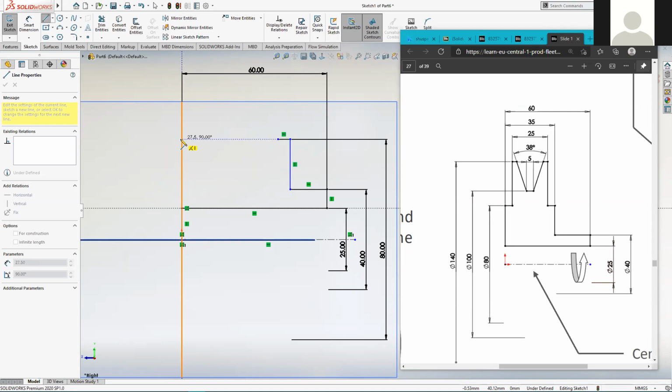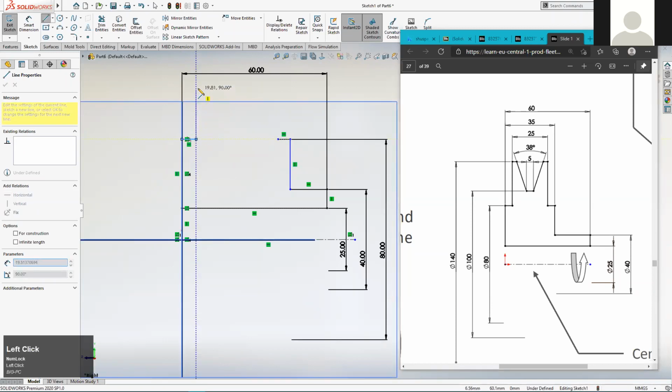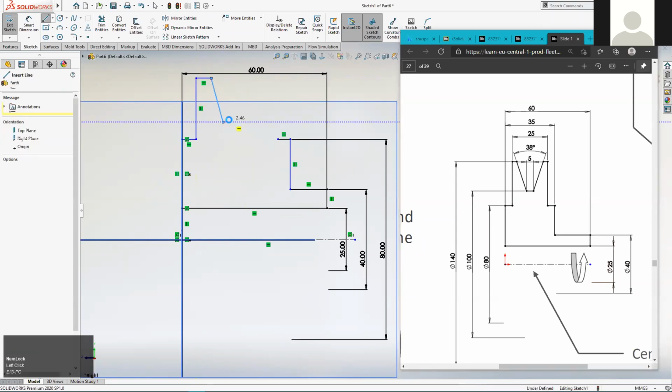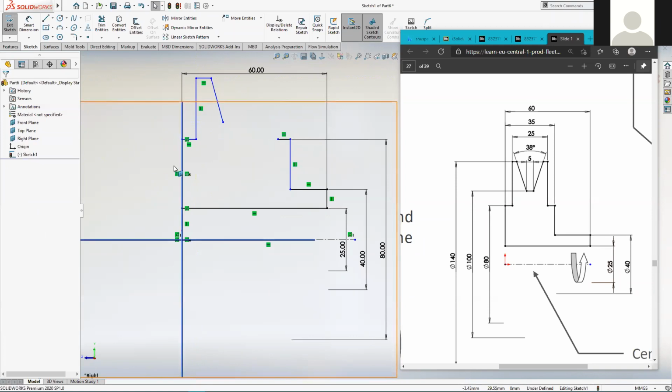That's just for my reference, so that's quite useful. So I'm going to click there. Then I'm going to come in slightly because I'm creating a little step. And then I'm going to go up a little bit, up to about there, and click again, and then along, and then maybe I'll put half of that V shape in, something like that. And then I'll press escape, and I'll start putting some more dimensions on this thing, hopefully.